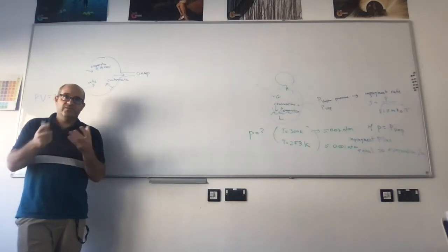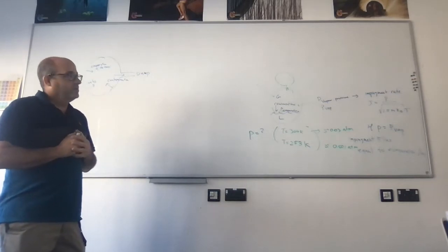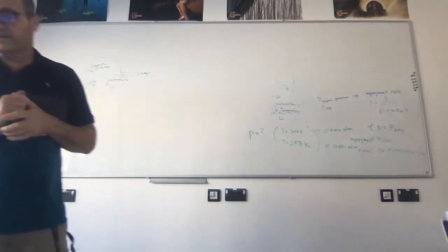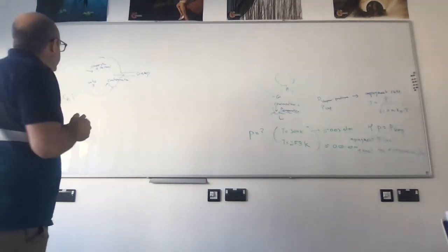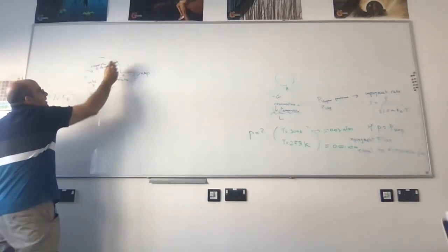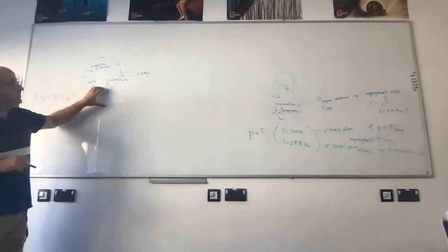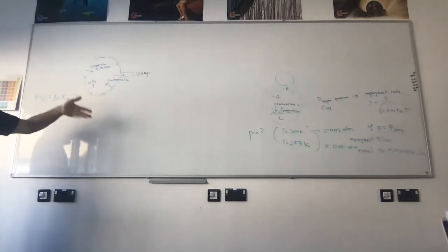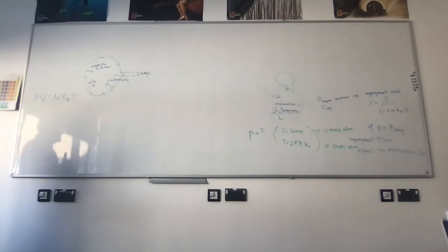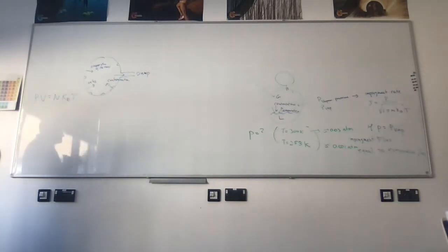So this is worth knowing. You probably had all the ingredients to know it, but hopefully it will sit a bit better in your heads now. So why did I mention this? I mentioned this because you remember when we closed the chamber, we were speaking to a friend and spitting a little bit while doing it, as people do, and we had some water in our chamber, which means that we're going to have a pressure here. We can pump it, but all the time water molecules are being evaporated, okay? And as long as there is liquid water here, the system will tend towards vapor pressure, okay?